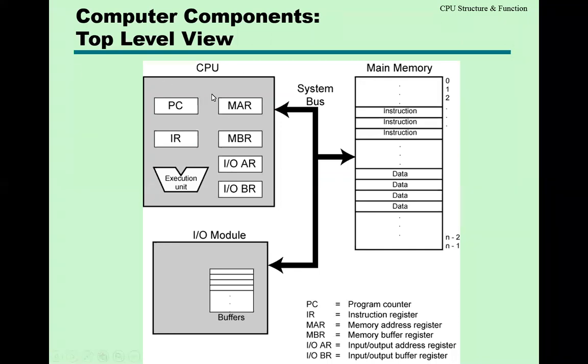The PC holds the address of the instruction and the same address is loaded into the MAR, and then the system generates a read signal to read the instruction address from the MAR. After generating the read signal, this address is read from the MAR register and a particular instruction is taken from main memory.